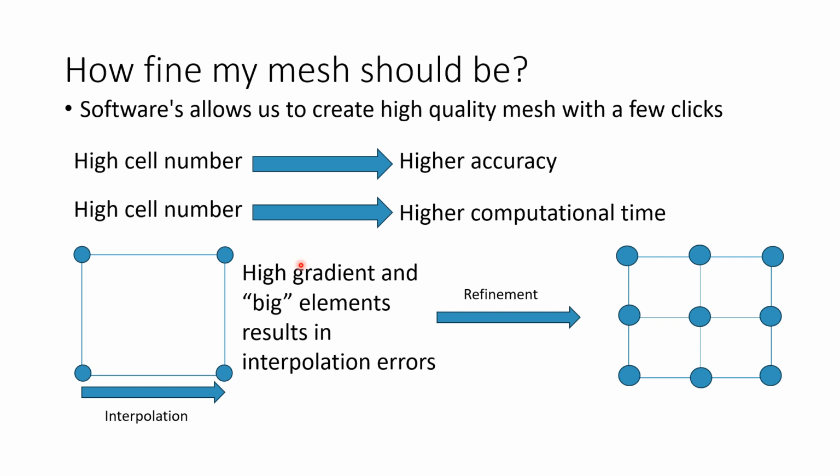like a guidance. So here is a cell. Here are the nodes. The nodes are the so-called computational points of the solver. In these nodes, the solver will calculate its equations, whether it's a static structural solver, an explicit dynamic solver, or a thermal simulation solver. They are basically the same. So here is one node, here is another node. How will the other node know what the previous one calculated?